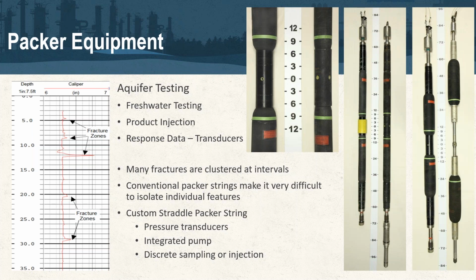So these are places where we want to, again, start at the bottom and work our way up out of the hole for injection. But there may be cause at this site or another site to walk the packer up and down that hole, injecting if there are secondary porosity concerns. So this packer equipment is really the heart of the downhole system. The injection truck is the heart of the above-surface system, what we see most of the time. I'll show you that in a few minutes.